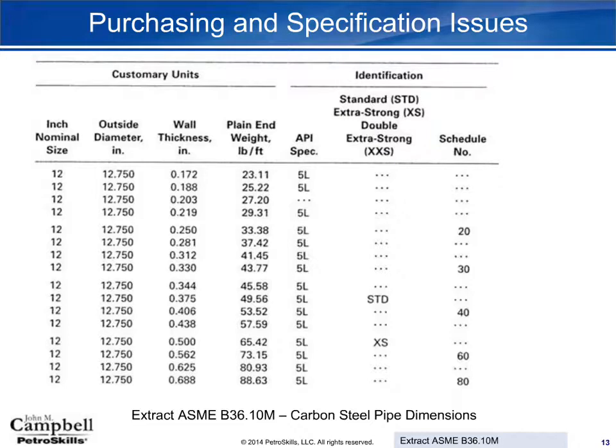And I've just, of course, again, 12-inch pipe, taken the section out of that code. And really, I just want to point out that there is a significant difference here between Schedule 40 and standard wall, and Schedule 80 and extra strong. They're not the same thing, and I've seen many a mistake occur from assuming that they are the same thing.